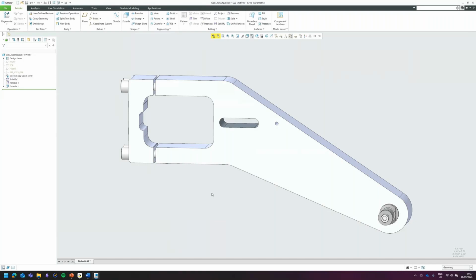One thing to mention is also these are saved in the customization.ui file. So you can maybe generate a company list of presets and have that UI file deployed across your users. So that is a capability as well. You can have some company standards, maybe notches for bend lines in your sheet metal work, or company logos, extrudes for embossing your logos, those sorts of things.